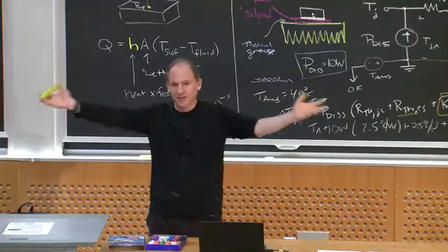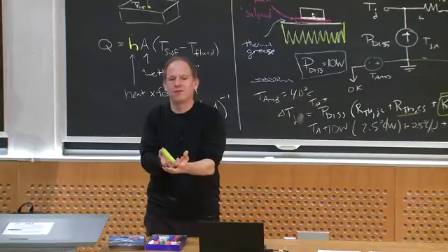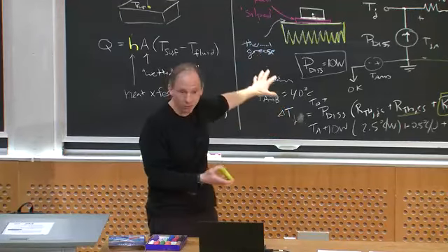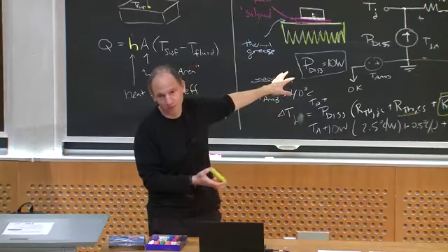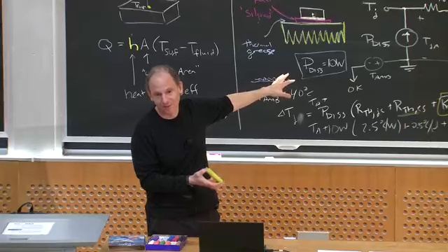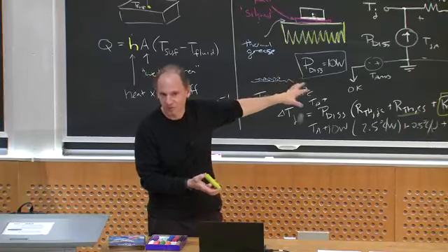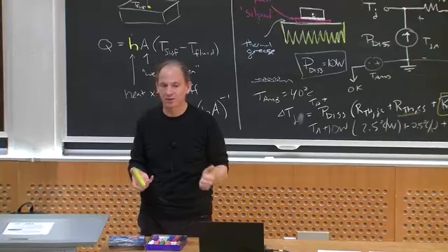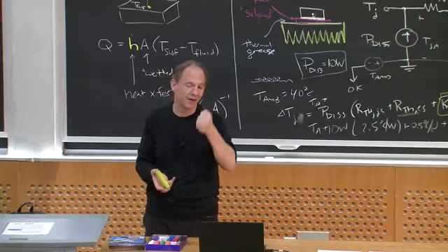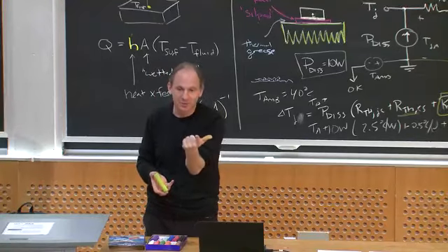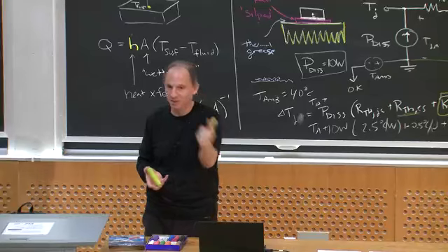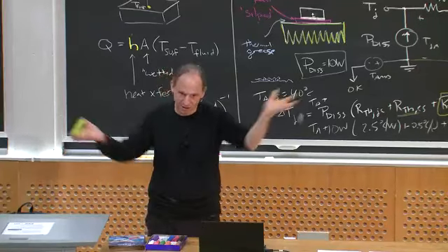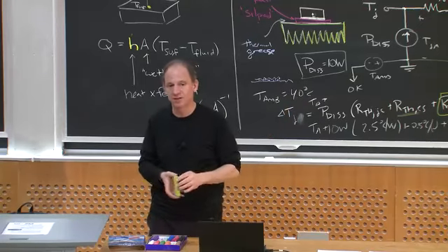At a broader scale, if you have to consider the whole thermal design, either you get a bigger network or you start to pull out computational tools like finite element tools. But very often for a power converter design, in a buck converter, you might have your MOSFET and your diode as big sources of loss, and then maybe your inductor is next, right? And you just model those into the system and figure out how you're going to heat sink it.